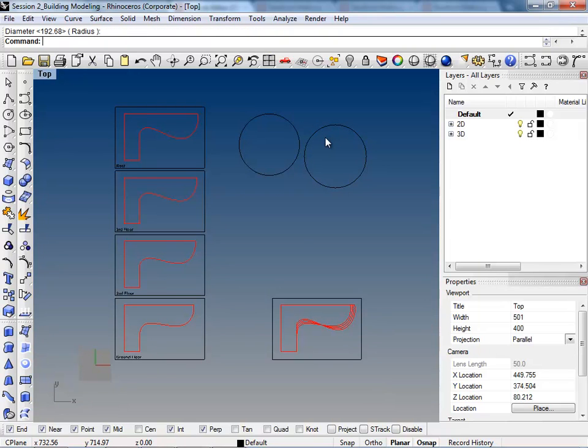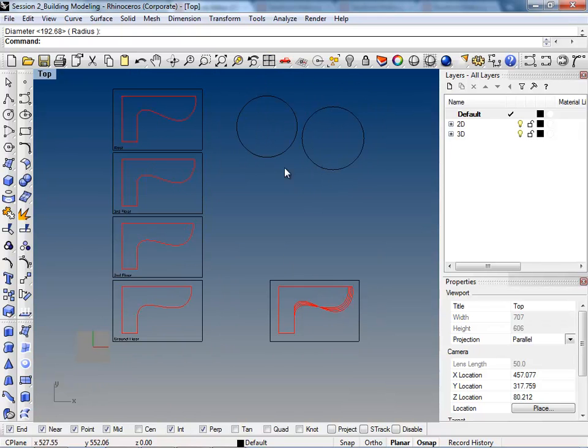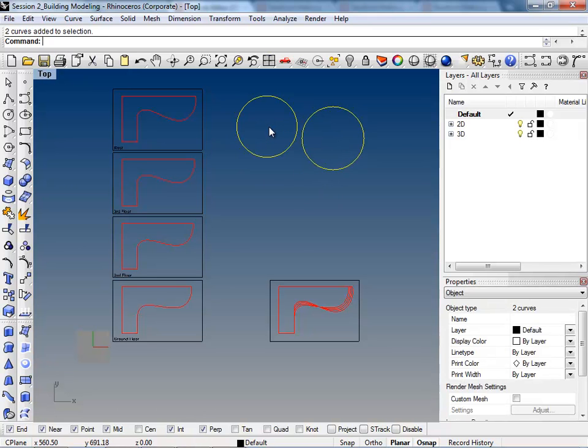Let's say you want to join them like that, like a U curve. You mean you want to create a form between them, so you're just creating like a horseshoe? Yes. Well, an easy way to do that would be to go into the front view, draw the U-shaped curve, and then do an extrude. Yeah, extrude along the curve. That makes sense.